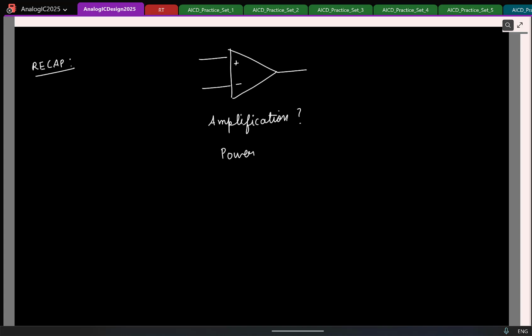right? And for getting power amplification, what kind of devices do we need? Linear or non-linear? Nonlinear, and we saw that we need nonlinear devices because in general we cannot generate any power of our own. The only thing we can do is convert energy from one form to the other. So with a nonlinear network, you power it with a DC source. So you drop DC power and basically convert some of the power to the signal power, and that's how we get large signal power, right?